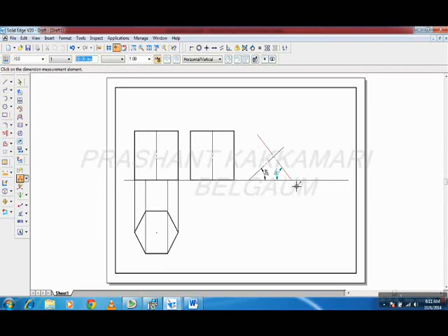So in spite of that, what you can do is, just draw one line at 50 degree angle. So this line itself is the base line, and midpoint of this base, see here, this is the midpoint, or whatever the line length is, you measure it and cut it at some midpoint. So from this point you can draw the axis in hand sketching. So I think it is clear now.